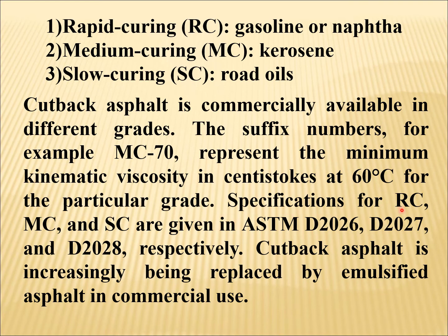Specifications for rapid curing, medium curing, and slow curing are given in ASTM D2026, D2027, and D2028 respectively. Cutback asphalt is increasingly being replaced by emulsified asphalt in commercial use.